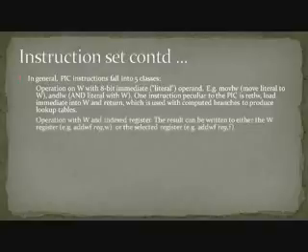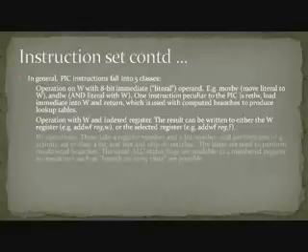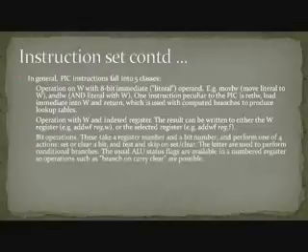Second, operation with W and an index register. The result can be written to either the W register or the selected register. Third, bit operations. These take a register number and a bit number and perform one of 4 actions: set or clear a bit, and test and skip on set or clear. The latter are used to perform conditional branches.